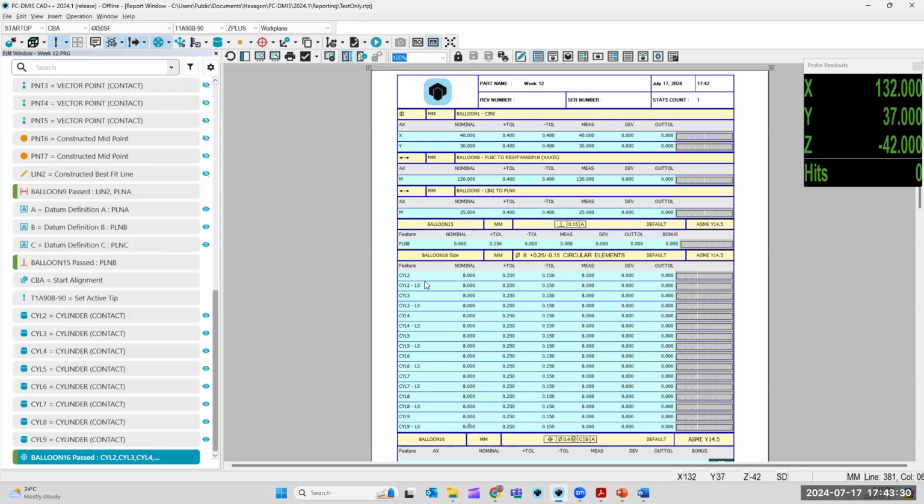I don't know how to change that default. I've never seen or come across it, so I'm not sure you can. So you're going to have 2 dimensions for the exact same cylinder every single time. They all should be in spec. If it's not in spec at the bottom or the top, there's something wrong with that cylinder. It wasn't drilled correctly or machined correctly.